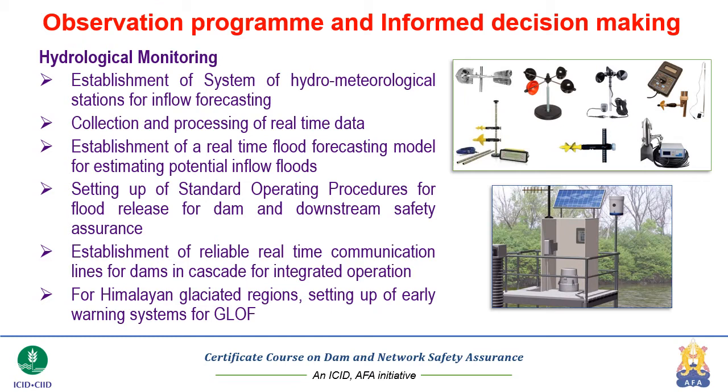so that you have a quantitative idea about the volume of water that is likely to come in the reservoir, where it will lead to the reservoir levels, what kind of outflow strategies will have to be adopted so that the dam remains safe, and you are also in a position to provide forewarning to the downstream areas for their emergency action planning, that these levels of outflows are expected at these points of time. So disaster management agencies can start their preparations well in advance.